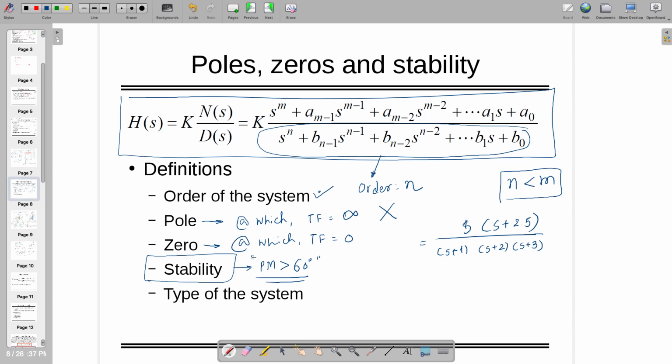Right? Now, the next part is the type of the system. Have you heard this word, type of the system? It might be new. I don't know. Not like linear, non-linear. In differential equations, there is one more term which is called type of the system. We electrical engineers use it very frequently. You have to see in the denominator how many Laplace operators or integrators are available. The number of integrators decides the type of the system.